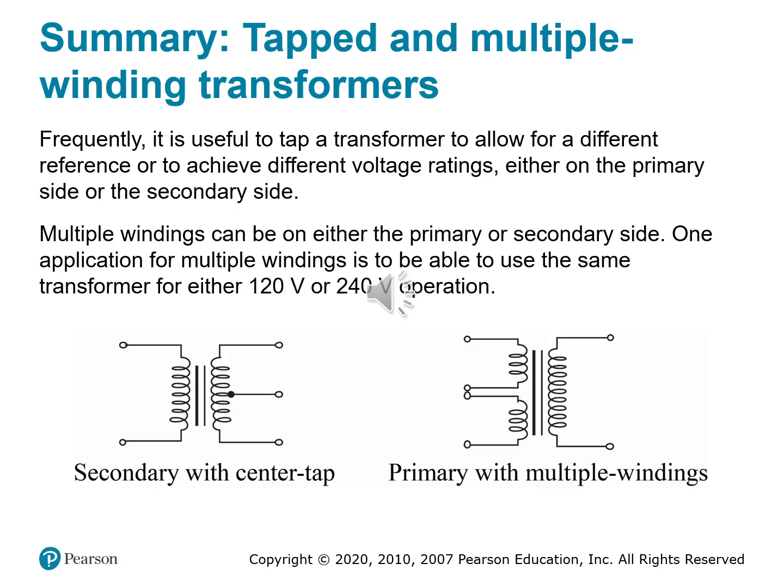The key takeaways here are: the taps let you access partial voltages, multiple windings provide multi-mode operation, and these features add versatility without requiring multiple transformer models. So next time you see a transformer with extra wires or labeled taps, you're not just looking at extra hardware, you're seeing a design optimized for adaptability.